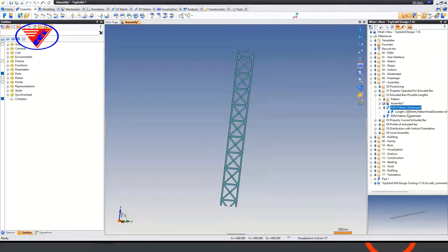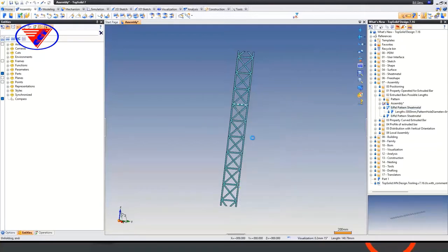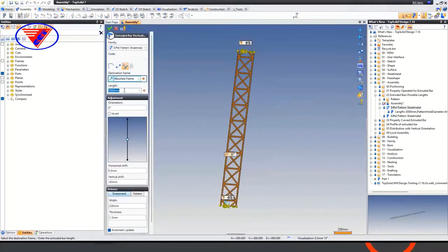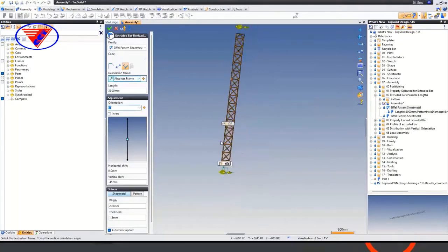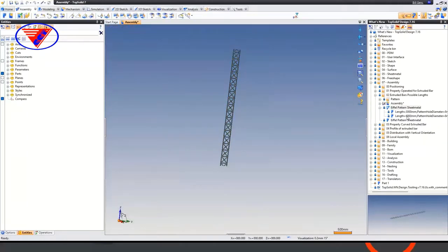Now, if I go and modify this, or create another one, it doesn't really matter. This time I say 3,300, or 3.3 meters. So obviously that got bigger. And here, again, now it's creating a 6 meter version of the part that it's modified. And again, this was an optimization to help speed up the performance when using extruded components, let alone complex extruded components.